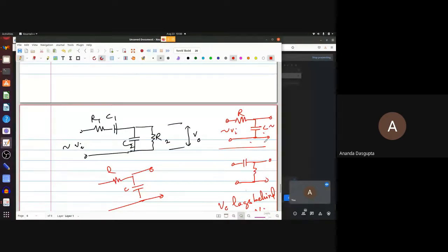If you look at this particular circuit, now this is not a simple RC or CR circuit. It's more complicated than that. I explained this in the video, but maybe it's important to repeat that. With the capacitance, you all know that the impedance depends on the frequency. When the frequency goes down, the impedance of a capacitor goes up.